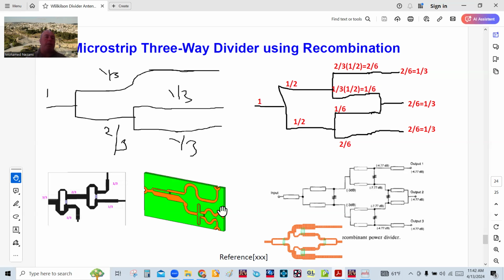So in case of beamforming, somebody might say, why don't we lump it into the beamforming weights in there? So all the Taylor and Chebyshev weights can be incorporated into the magnitude of the complex beamformer values. And of course, you can do that. However, you really lose resolution, because then you end up with one weighting over another weighting, which is probably not nice. So you still want to do tapering statically, better than doing it in beamforming. And in a lot of cases you get antenna arrays where they're not really beamforming, like in the case of 5G and 6G panel antennas, okay? A lot of them get a fixed beam to cover a certain sector, but still, you want to control the side lobes, therefore you resort to tapering.